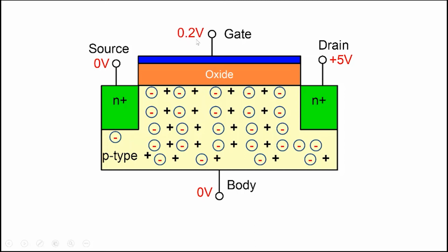All right, so when we apply a positive voltage here, note that this positive voltage will create a field pointing down into the semiconductor and will push away the holes. The holes are mobile and they'll react to the field and will be pushed away. The positive charge will come and sit over here. So this region will be depleted of holes, and you create a depletion region because the positive charge has been pushed away and removed to the gate. And so this region becomes charged. It leaves behind the ionized acceptor atoms here, negatively charged.